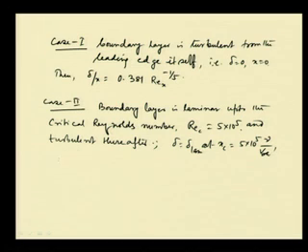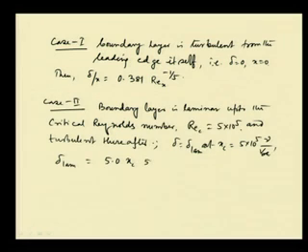Delta laminar basically is equal to 5.0 into x critical from the exact analysis, 5 into 10 to the power 5 whole to the power minus half. This is from exact analysis.